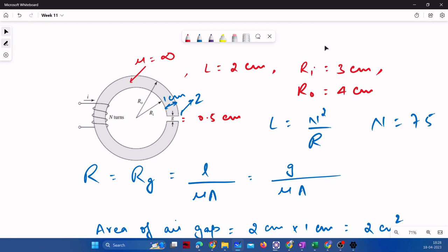So then you have to play on the air gap side, or number of turns, or current. So you have two or three degrees of freedom. If you have flexibility on current, like you have a higher limit on current, then you can go with a higher air gap as well. You need to see during design how much limit is there with you, how much extent you can go.